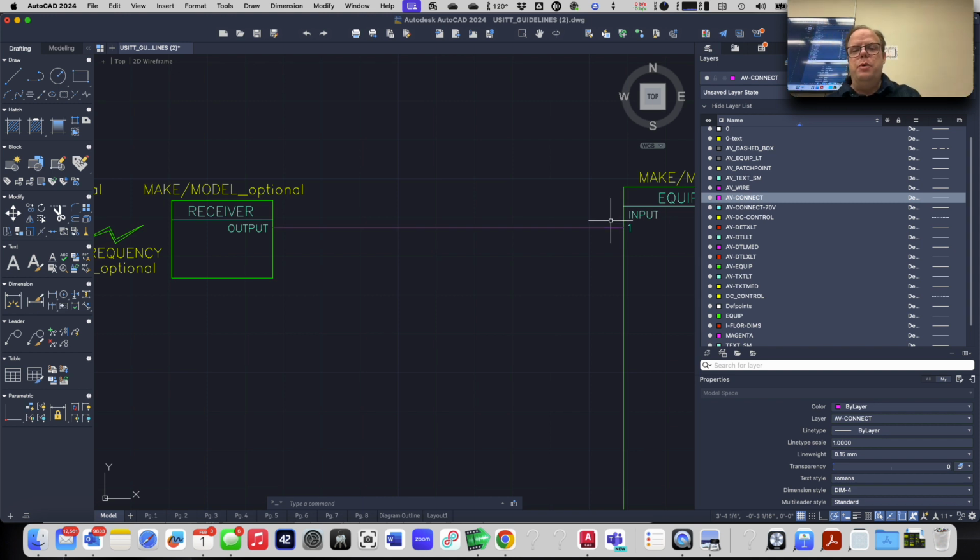Okay? So here's what we're going to do now. Now I can get rid of it. I know that little tiny line is there, even though it's on top of the other one. So I'm just going to go ahead and select it. I'm going to do a blue drag right to make sure I just get that little extra line that I don't need to have there anymore, and then hit E, enter to erase it. Okay? Everybody with me?